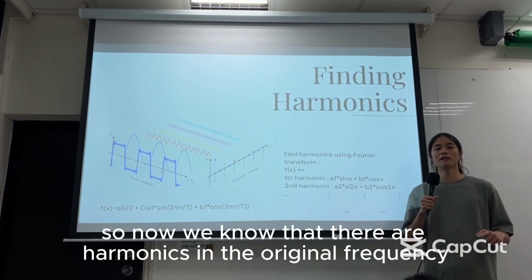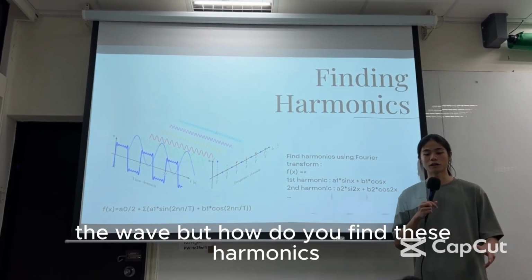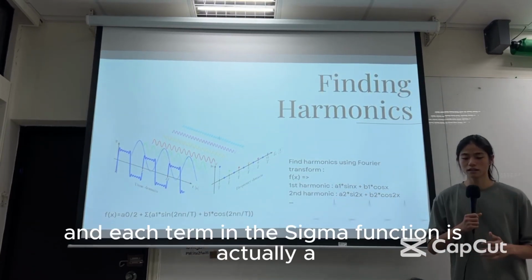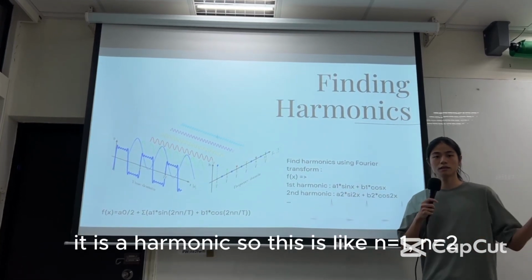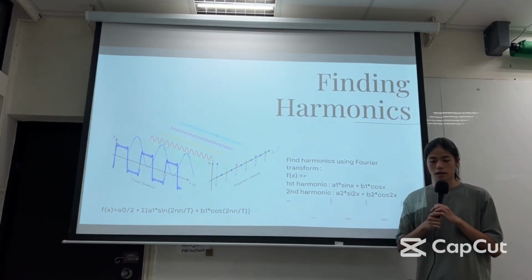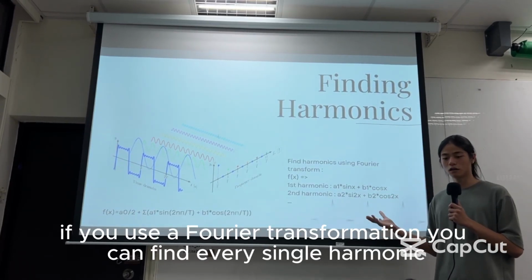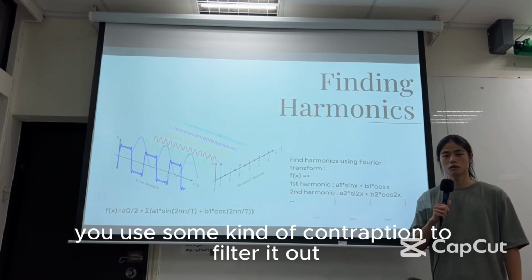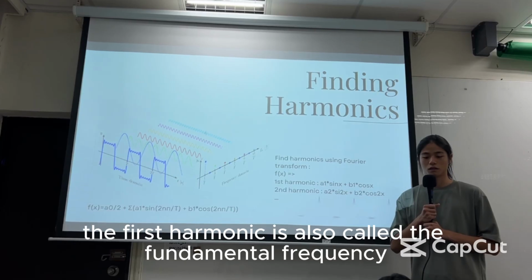So now we know that there are harmonics in the original wave. But how do we find these harmonics? Well, if you remember the formula for the Fourier transform, it looks kind of like this one. And each term in the sigma function is actually a harmonic. So this is n equal to 1, n equal to 2. If you use the Fourier transform, you can find every single harmonic. And then if, say, you don't want the third harmonic, you use some kind of contraption to filter it out. The first harmonic is also called the fundamental frequency.